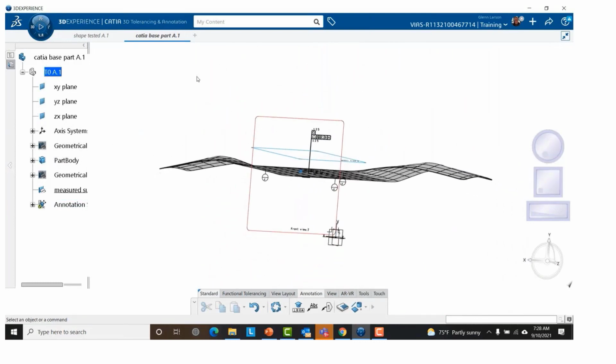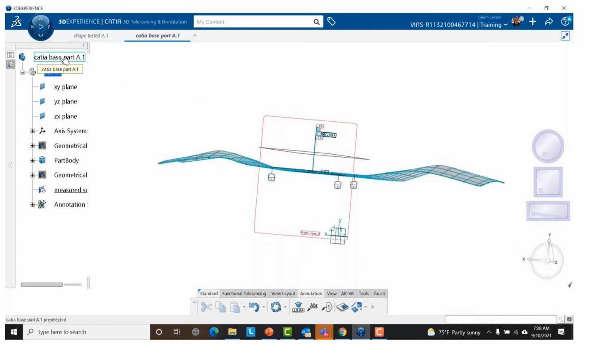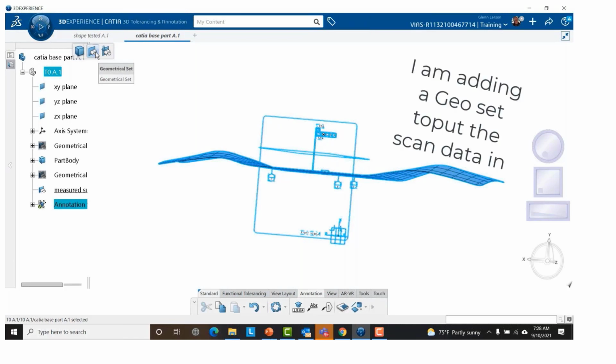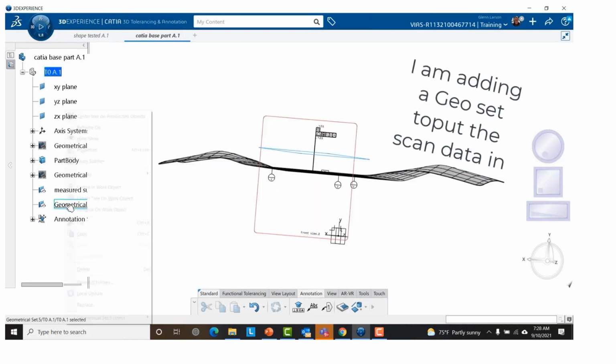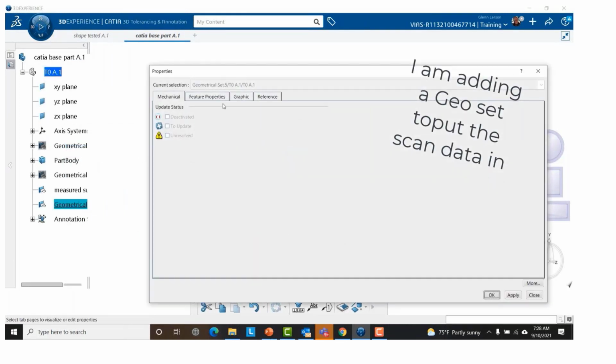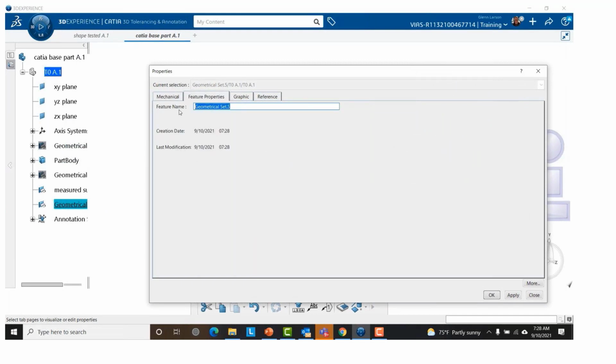And we're just going to go ahead and create a new geometrical set to bring in some digital data. Now here I'm bringing in an STL file, but this file could be, again, anything. It could even be from an Excel spreadsheet of points. So somebody could use a CMM machine and take points, and you can get the same thing. The more points, the better.